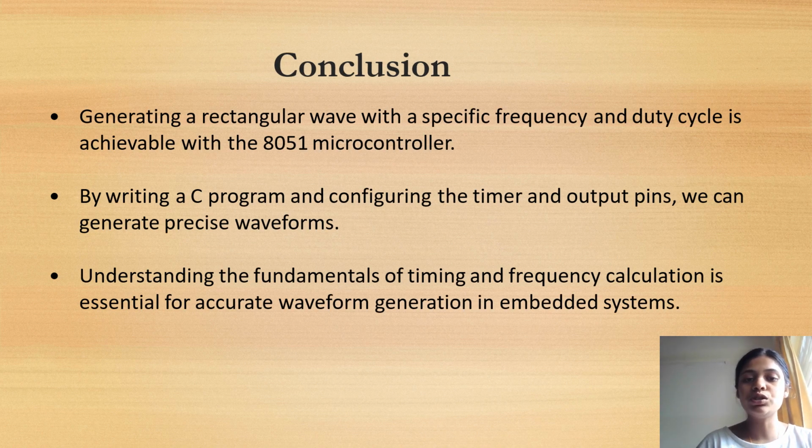At last, we will go through the conclusion. Generating a rectangular wave with a specific frequency and duty cycle is achievable with the help of the 8051 microcontroller. By writing the C program we have discussed and configuring the timer and output pins, we can generate precise waveforms. Understanding the fundamentals of timing and frequency calculation is essential for accurate waveform generation in embedded systems.